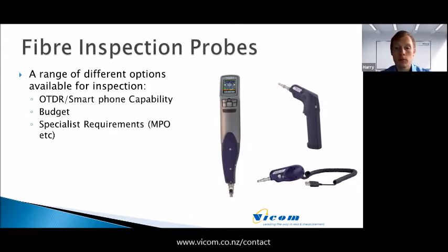Other considerations to think of when you're looking at getting an inspection probe is, do you want one that works with your particular OTDR? So in the case of Viavi, you can look at a P5000i inspection probe, which will work with any of your Viavi OTDRs. Additionally, you might want to look at specialist requirements. Are you inspecting a special type of connector, for example, MPO connectors? For those of you who don't know, MPO connectors are essentially a connector where multiple fibers run to that connector interface, anywhere from 8 to 32 fibers. So you can get specialist tools like the Viavi Sidewinder to inspect all of those fibers simultaneously, once again with autofocus and auto centering capability.